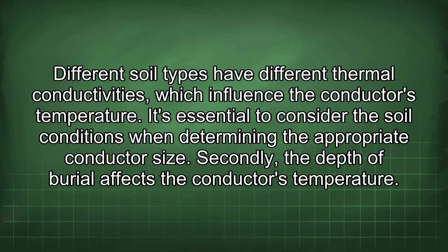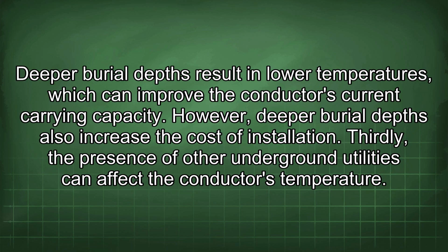Secondly, the depth of burial affects the conductor's temperature. Deeper burial depths result in lower temperatures, which can improve the conductor's current carrying capacity. However, deeper burial depths also increase the cost of installation.